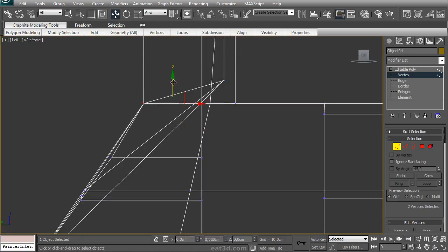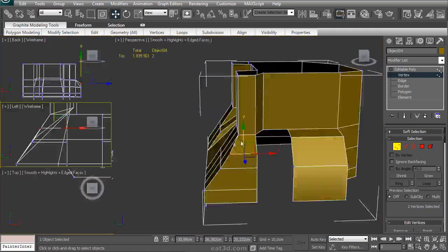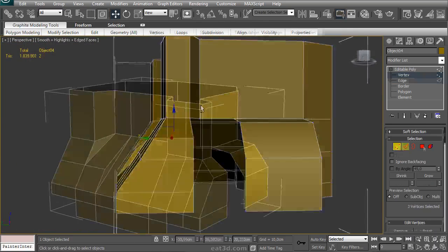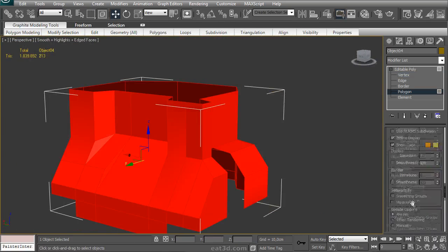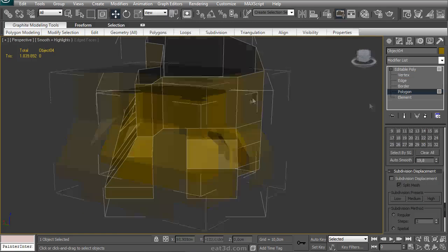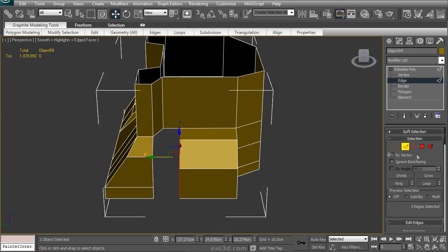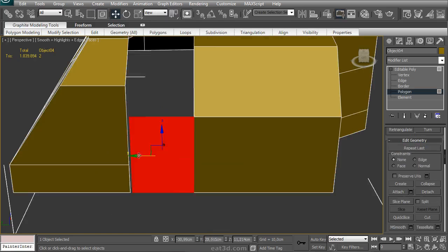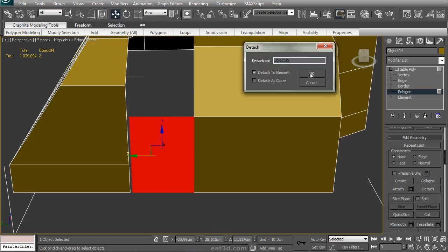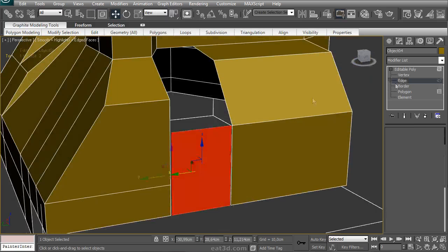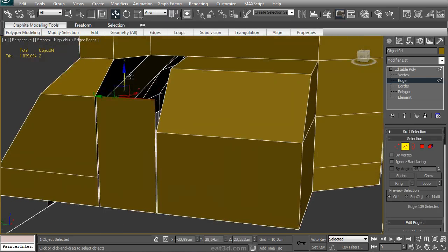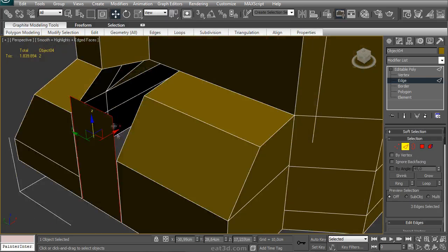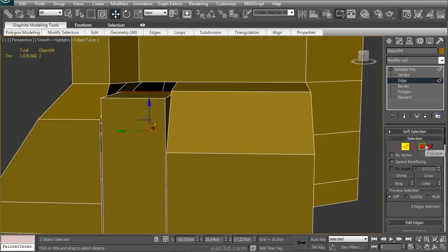Right, so I'm moving these verts up a little bit to get everything aligned. You can see there's some sort of sloped surface here. And I want those to align with the back surface nicely. Then I set the smoothing groups right because it's just a lot easier to see what you're working with when you keep your smoothing groups updated. Then a small extrude here. And what's this for? Well, there's another box shape over here. And just simply creating that.